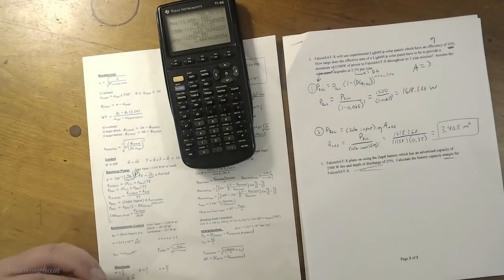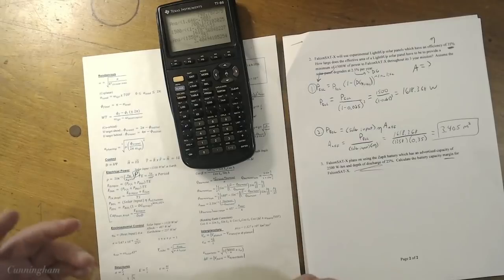If we had a depth of discharge of like 80%, that means we would be using 80% of the battery every time we were in eclipse. It doesn't give you much margin. It doesn't give you much extra. Like, what if you came out of eclipse and your solar panels, for some reason, weren't putting out as much power as you wanted? Maybe you were pointed the wrong way or something like that. You have to use your battery more. And, well, it would sure be nice to have a little more than just 20% left over. That's my example to you.